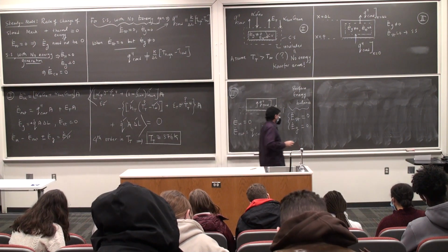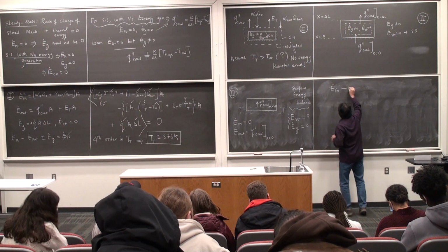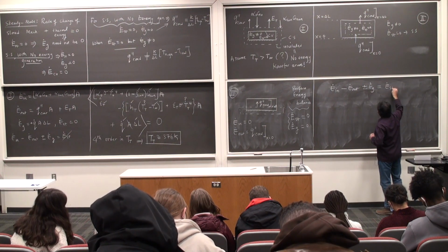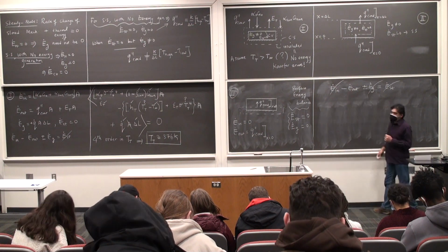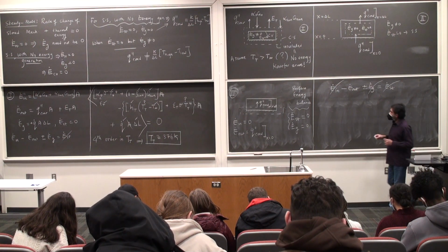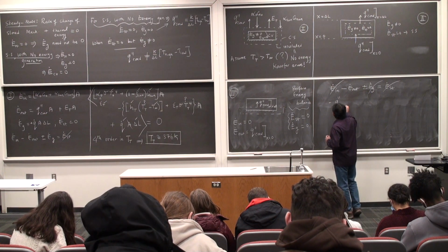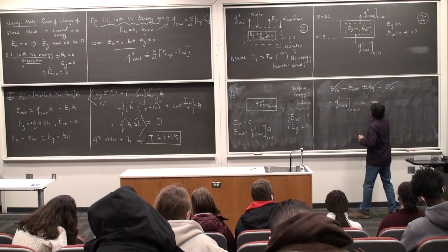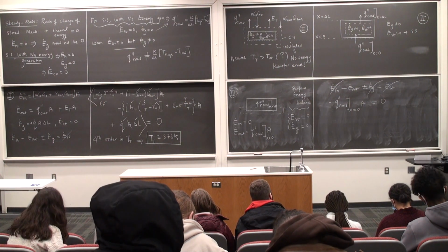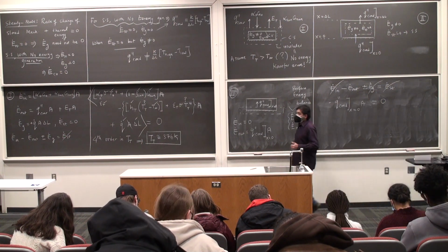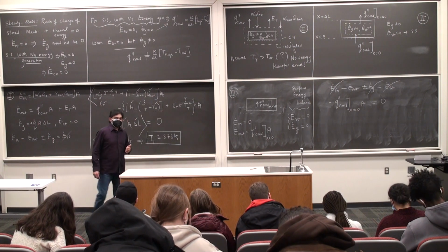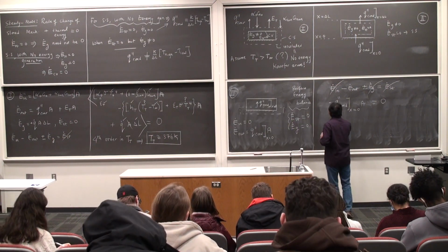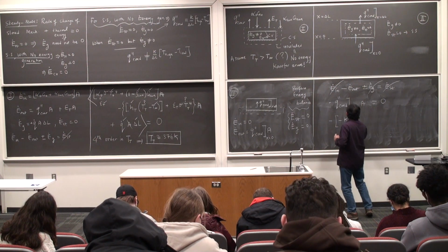I write the energy balance equation. All of these guys are history. I have only E dot out, which is minus Q double prime conduction multiplied by the area is equal to 0. This is where we bring in Fourier's law. If I just write it using Fourier's law, one-dimensional heat transfer, so this is minus k dT by dx.